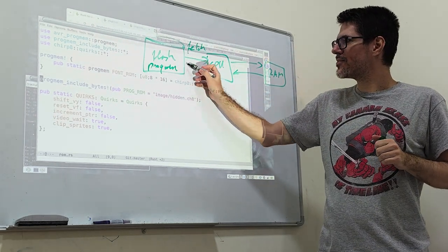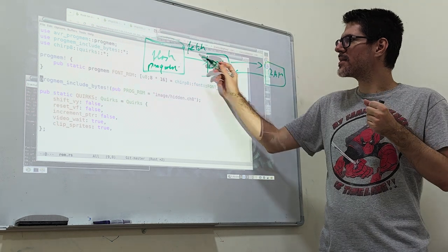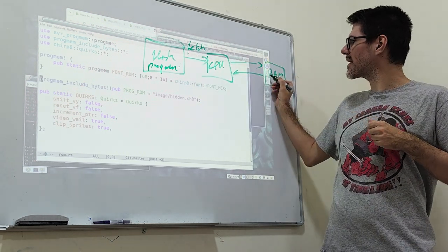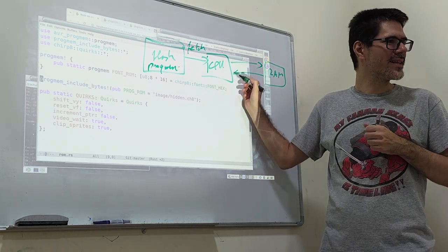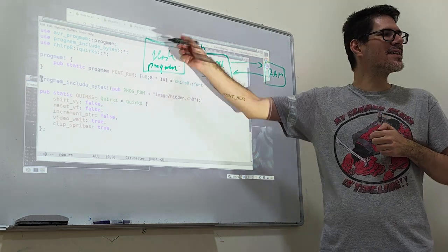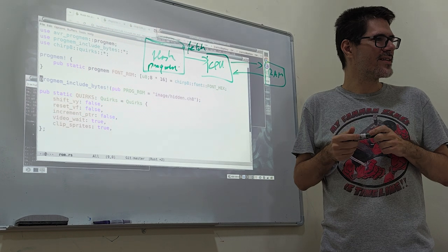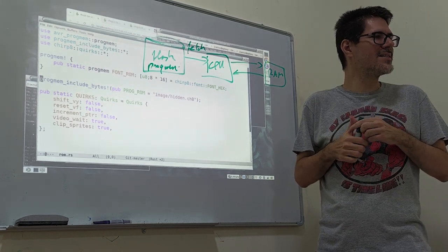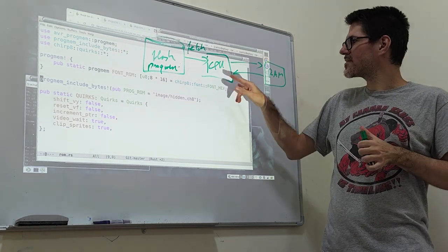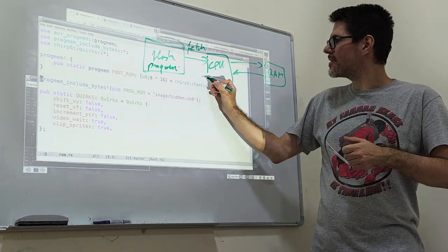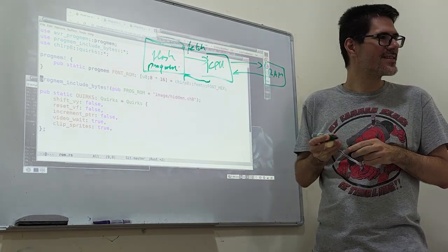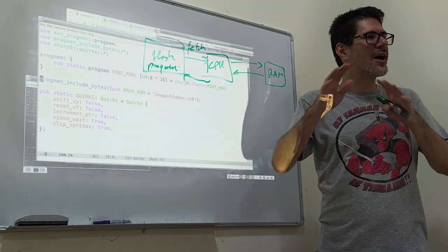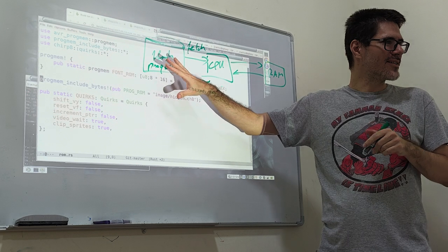So you can read bytes from here, but the important thing is that you can only fetch from here. There's no opcode to take in a byte and execute it, or take in a byte and pretend that is the next instruction, because the Harvard architecture has two different memory spaces. Yeah, that's what Harvard architecture means. Yes, it's not von Neumann. And you might ask, okay, what about this direction? What about writing into program? For our purposes here, you can pretend that you can't do that.